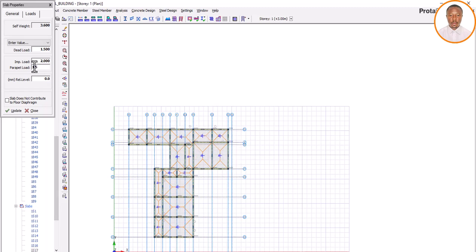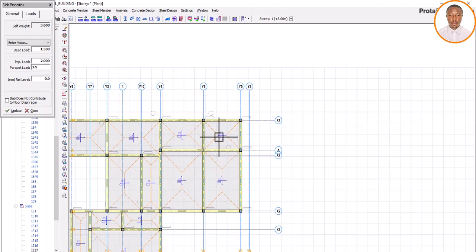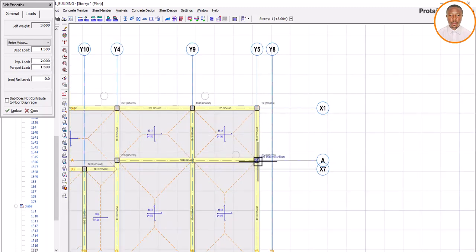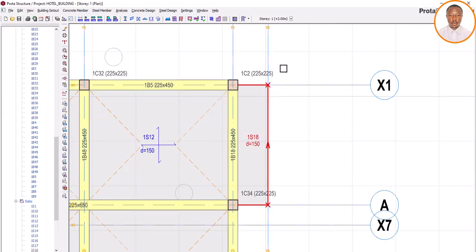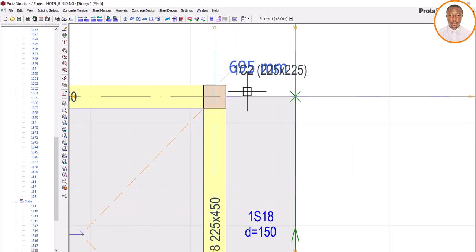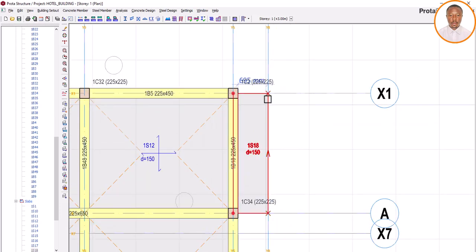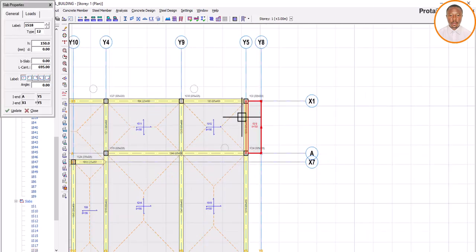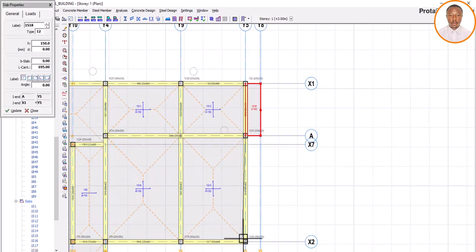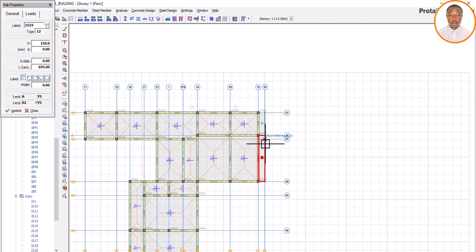To load this edge. So therefore, once this has been done, the next thing is to begin to insert, from this place to this place. Use it now. You can see this line. It means the line load is already on it. So let's confirm our measurement from this place to this place. You see, 695, accurate. Is that okay? 695, very, very accurate. So what I need to do, I click on this, right click, property, and begin to insert my column to column.